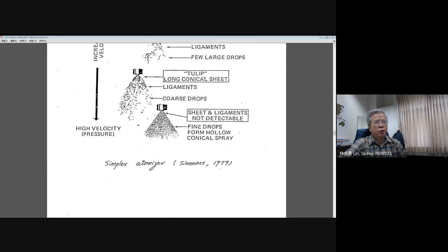Therefore, you will have droplets occurring starting from the vicinity of the injector, the exit plane of the injector. And this is good for our application because you just have many tiny liquid droplets existing in your combustion chamber. Then you can easily promote the gasification and further the mixing of the fuel vapor with oxygen from the air, then go through the combustion.